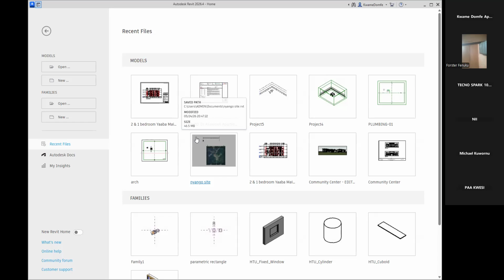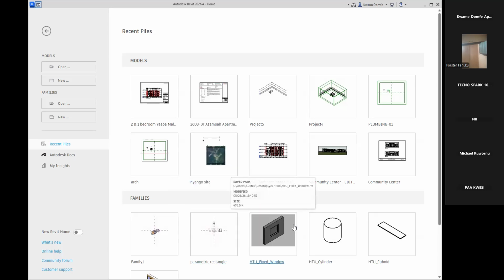If you have 15 sections, what time can you get to do those editing? If you have 2 sections, then there's a change in the project. What time are you going to get to edit all the 2D drawings that you've done? It becomes challenging. So please, those of you who are using detail items like hatch patterns to hide the details of their model should desist from it and then insist on doing a very good model for proper project delivery. So that is my take on the BIM. If you have any question, you can ask on BIM.